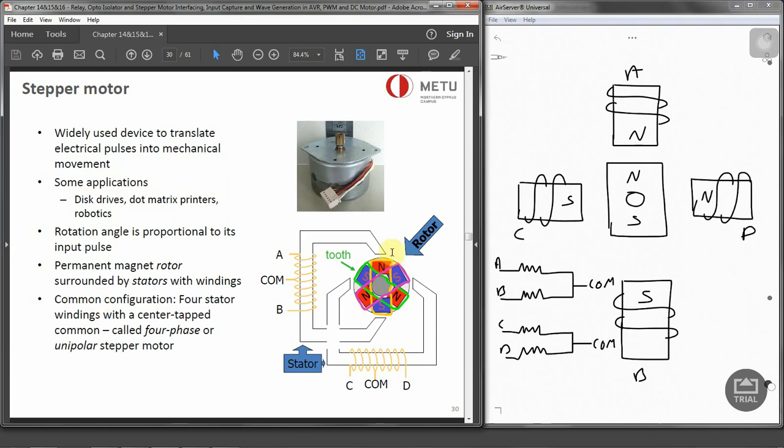As I already said, the difference between the conventional one and the stepper one is that it moves in repeatable increments, which gives us more precise position. This repeatable fixed movement is possible as a result of basic magnetic theory that you might see in your physics course, where the poles of the same polarity repel and the opposite poles attract.